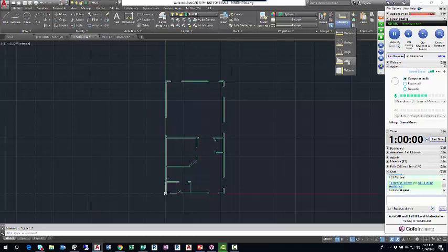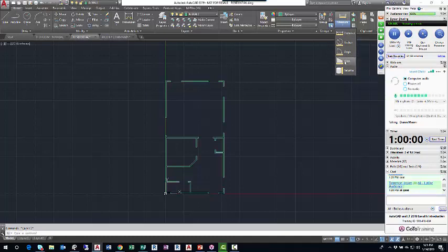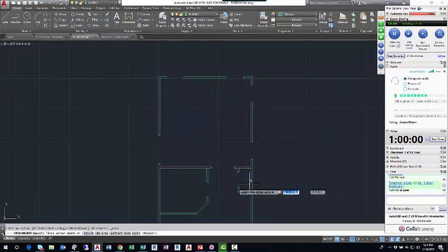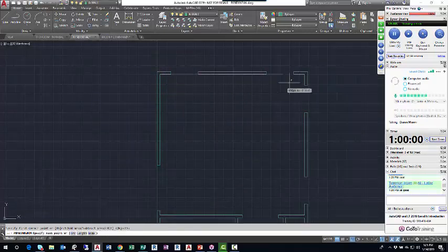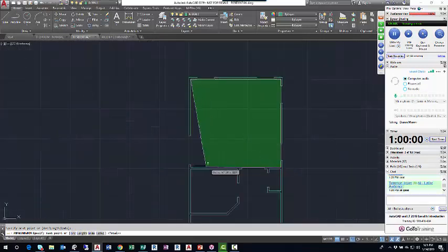All right, one other tool here that is very frequently used by people both in a site plan role and a floor plan role is area. I'm going to go ahead and left click area, and I'm going to click all four corners of the bedroom area. So I'll go one left click, two left click using my endpoints, three left click. As I'm clicking, this green tinted window is forming to show me where I've clicked.